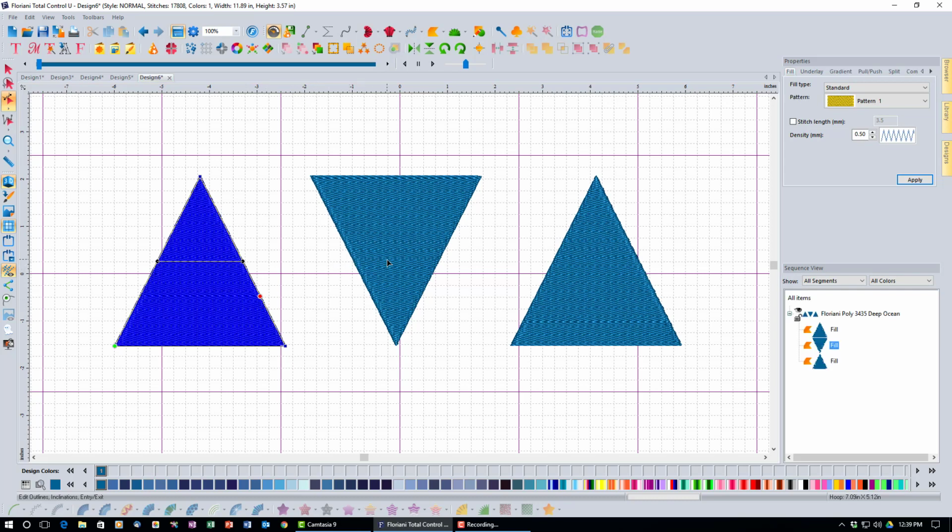So if I select that one, let's take a look. Yep, it drew a straight line across there. And then this one should do a very similar thing coming back to this one. Now put the stop point up here. So let's see what this did. Yes, my start point is right here, which is the closest point to here. So you can see that it optimized the start and stop entry exit points between all of these three elements.